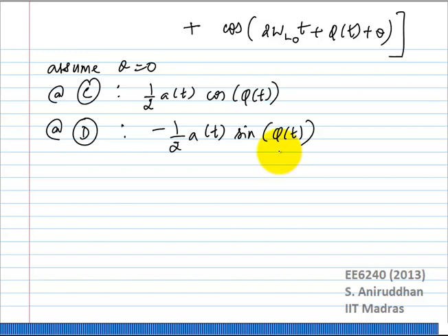Now you want to demodulate this. You want to get the signal. How would you demodulate this? You have I and Q. How would you demodulate the signal? Correct. So square root of I squared plus Q squared will give you the amplitude and tan inverse will give you the phase. So that is one easy way to extract the amplitude and the phase. Here we are assuming that we want to extract the amplitude and the phase.